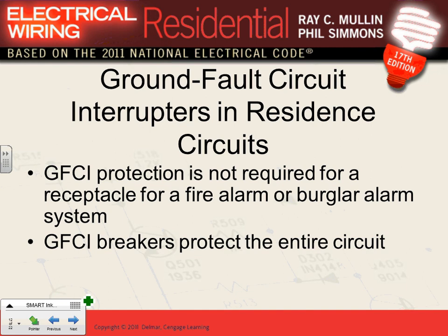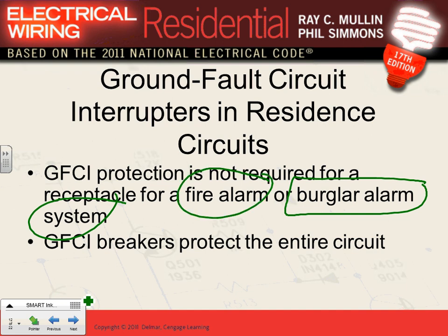Now, in dwellings, you don't need a GFCI for a fire alarm or burglary alarm system. That's an exception. So in your basement, if you have one receptacle where you plug in a fire alarm system or a burglary alarm system, it is excluded from GFCI.